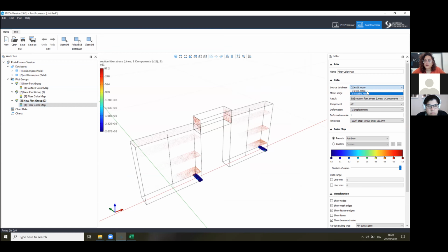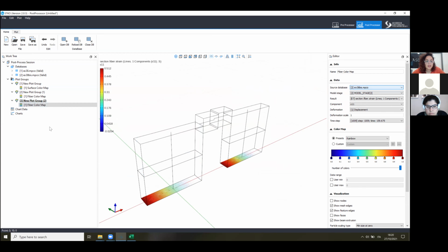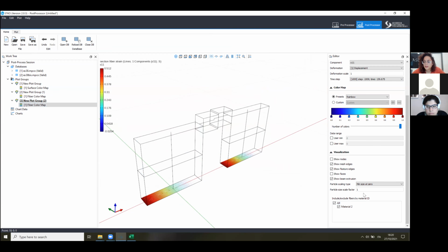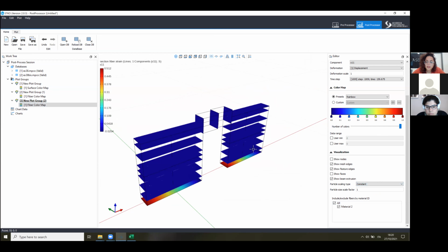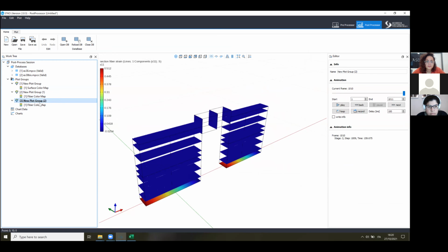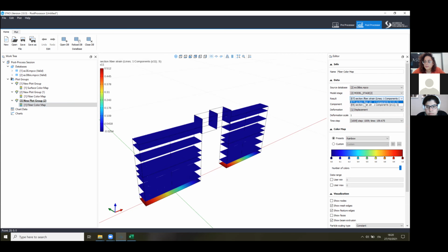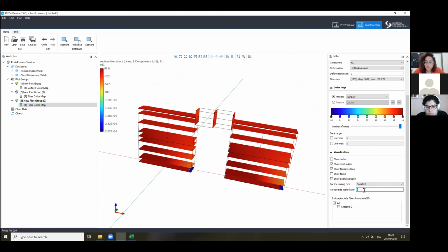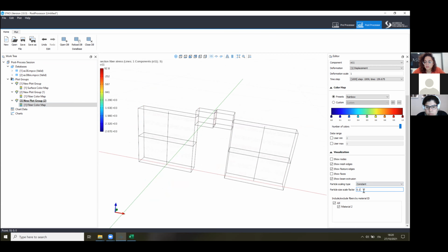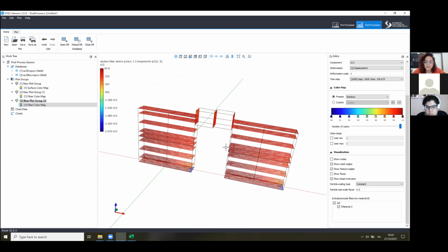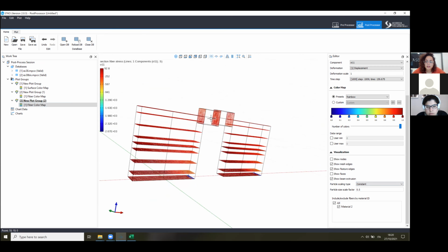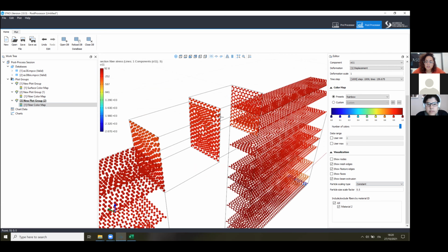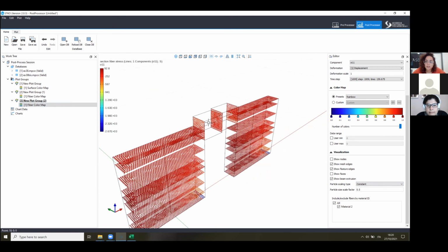So once we have our second option, here you can see how, let me give it a constant size. Yep. I have not just one place where my structure can break, but I have two. So let's make this fiber smaller. Yes. And you can see that my beam with shear hinge element created a hinge and lumped the shear behavior in the center of the structure.